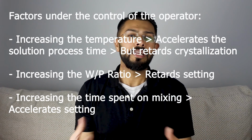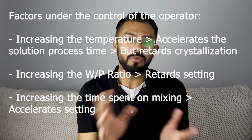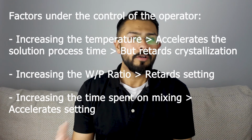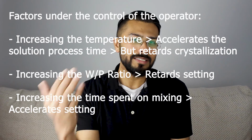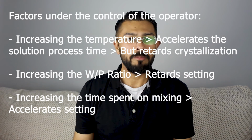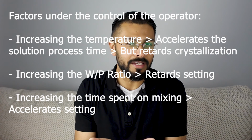Increasing the temperature accelerates the solution process but retards the crystallization. Thus, the two effects tend to cancel out. Increasing the water powder ratio retards setting by decreasing the concentration of crystallization nuclei. Increasing mixing time has the opposite effect. This accelerates setting by breaking up dihydrate crystals into more nuclei and more crystals during the early stages of setting.